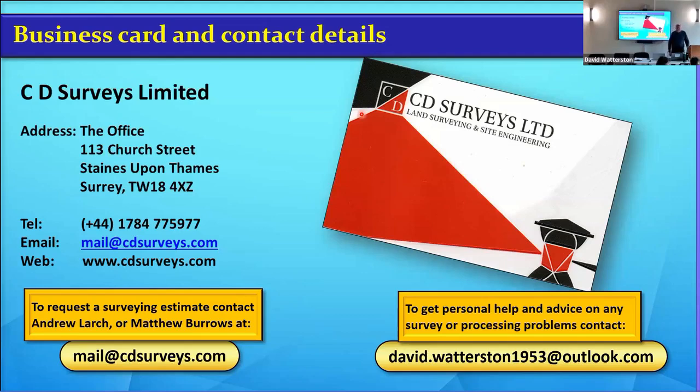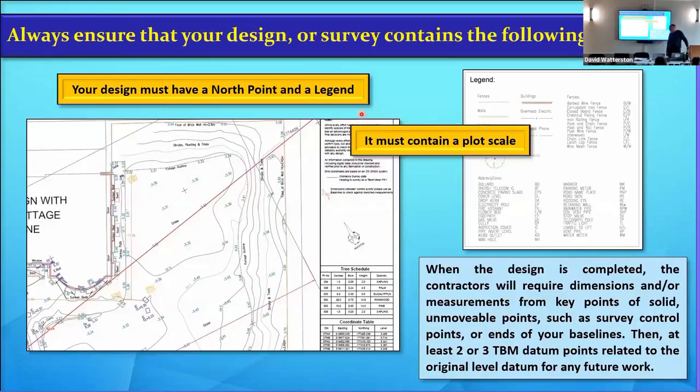Is the north on the plan true north? Grid, well, you get grid north, magnetic north, true north. So that is grid north, right? Which is more or less true north, because magnetic north moves about. It's all over the shop. Have you ever seen any traces over the last 10, 15 years? It went to Alaska and comes back.